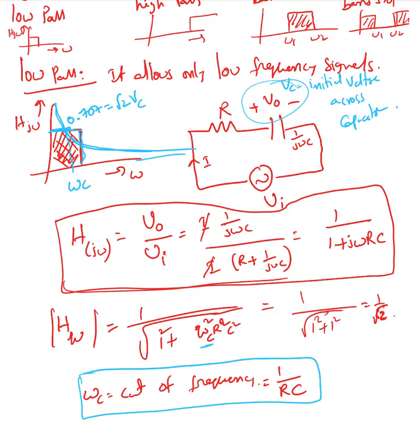I'm saying this is the low pass filter, but in reality with passive elements we cannot build a rectangle like this. The signal is going to go down exponentially in an RC circuit, because if you remember, a capacitor does not allow a sudden change in voltage. At low frequency, say frequency is 0, that means it's a DC supply.